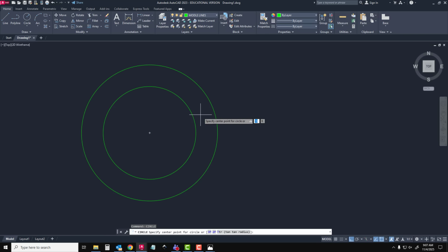If I move my cursor to right there, now if you look down here, this right here is going to be causing snap reference lines. This is really helpful. So I'm going to go right there, and I'm going to start making this little line right here. Now I'm going to type in 54, because that's the distance to that circle. I'm going to type in diameter. Now it's a 10 radius, so I'm going to type in 20. And now I have that circle in the right location.